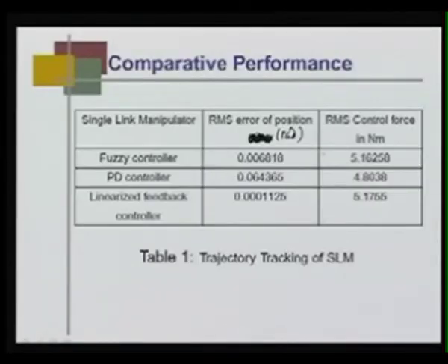If I want to compare the comparative performance, you see that the fuzzy controller is comparable, because we are applying almost the same control input: 5.1, 5.1, 4.8 Newton meter. This is the root mean square control force.